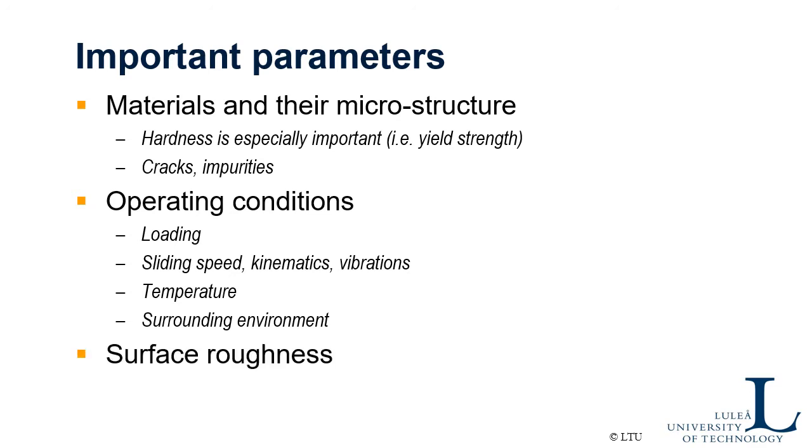Surface roughness plays a role here because surface roughness also creates the contact conditions, the contact mechanics of the surfaces. Surface roughness determines the local stress concentrations, and for that reason surface roughness is important here.